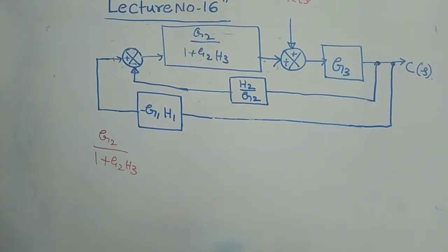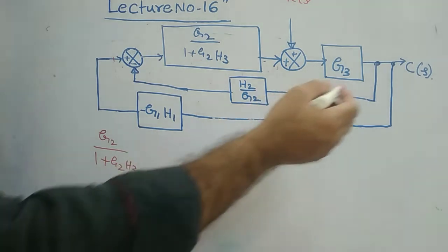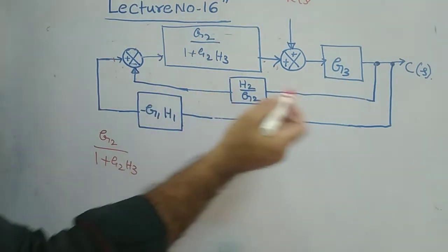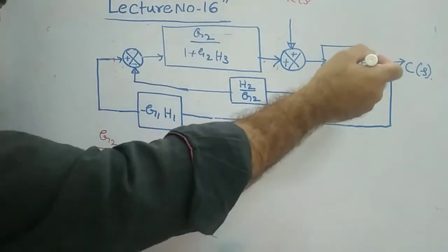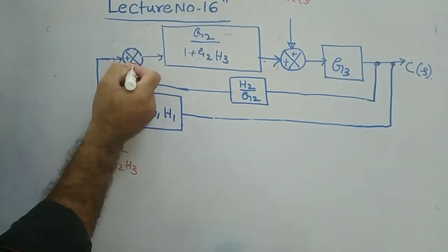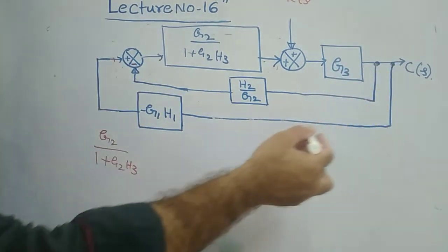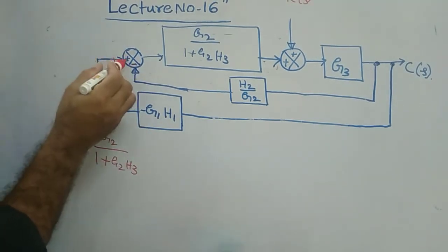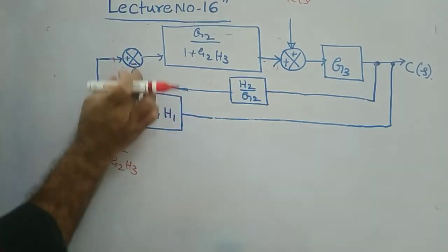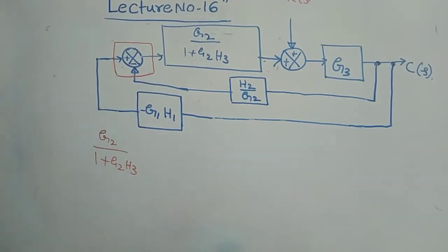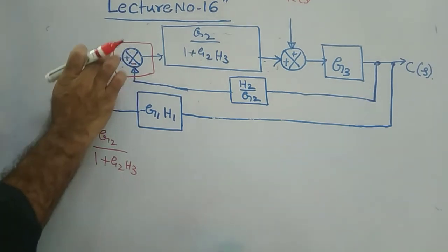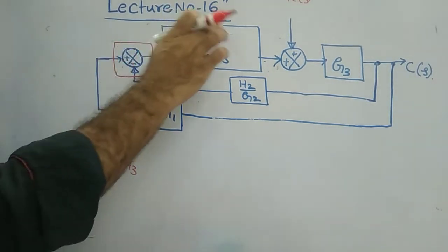Now carefully you see. So this is the feedback that has come. So this is the feedback loop coming from the output. It is going to this summer, and again this is the feedback going to this summer with plus sign. Means the same feedback loops are adding here. Both will be added here, and that total equivalent is in series with this block actually.